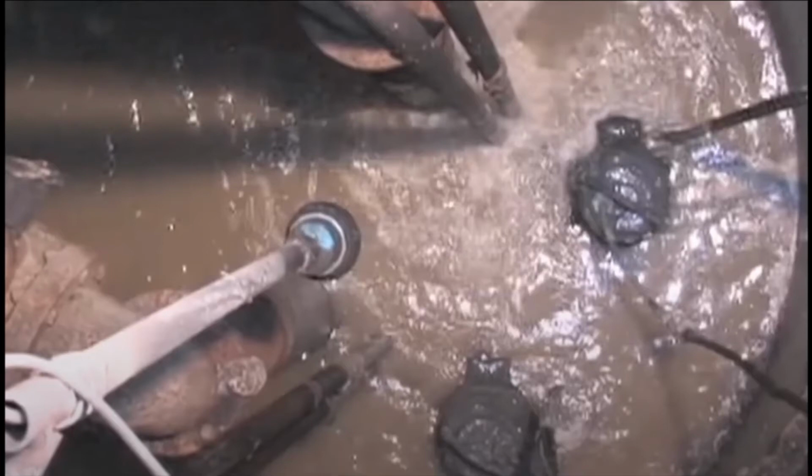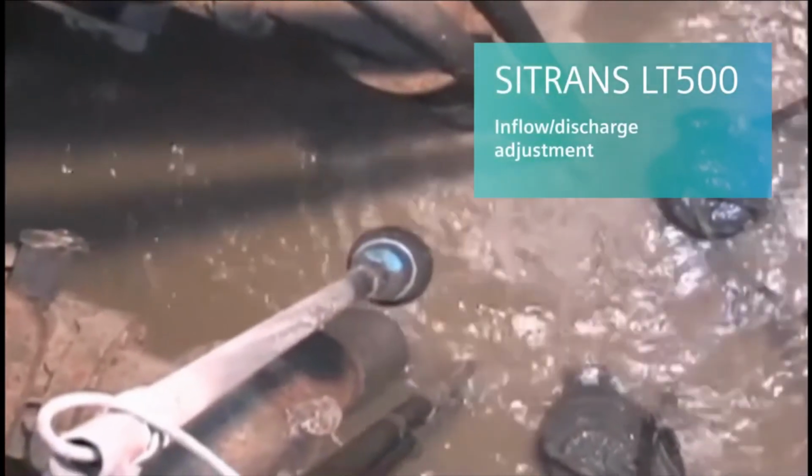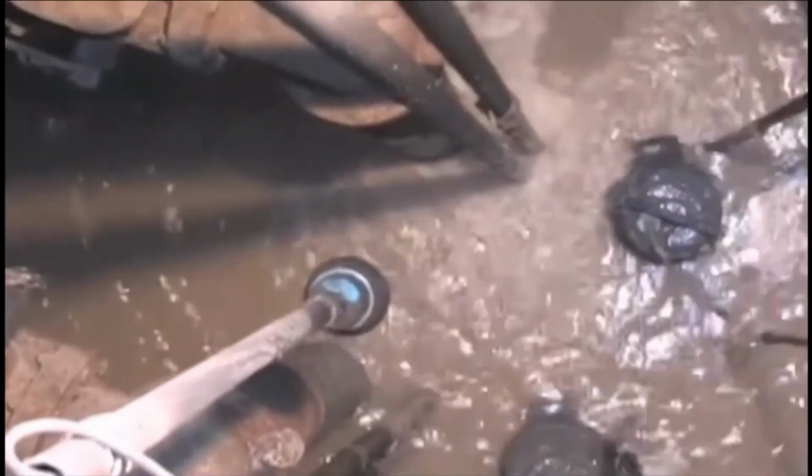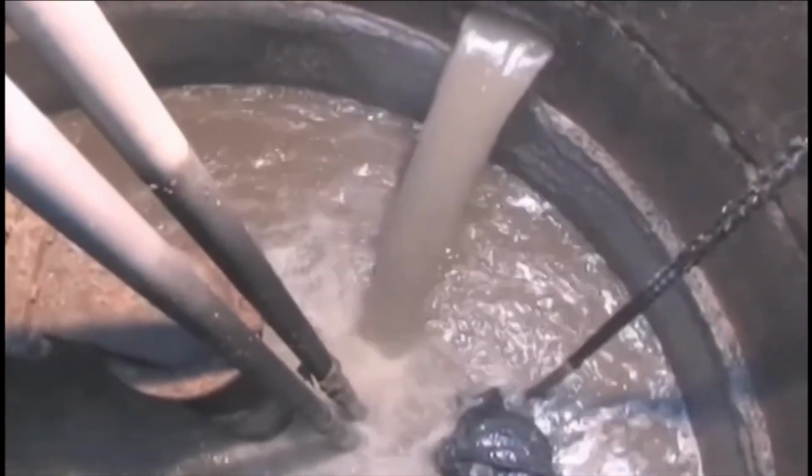By changing the on and off set points, we ensure that buildup does not occur in the same spot over and over again, creating an obstruction which could be seen as a false reading. We also reduce the maintenance on the inside of the vessel, increasing safety. The inflow or discharge adjustment helps to account for material that is being removed from the vessel while the pumps are running. It helps ensure that it is an accurate pumped total.